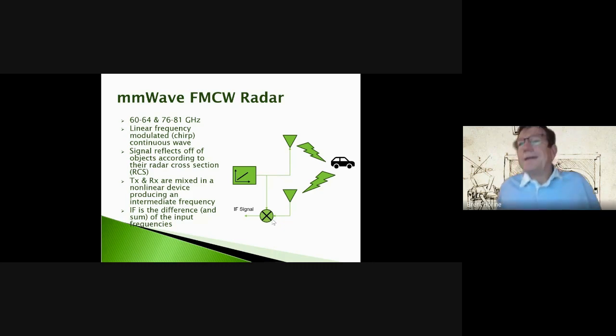I cover this in more detail in my communications course or my microwave course. But what you end up with out here, if you go through all that math with those trig identities, is that the signals at the output of this nonlinear device are the original signals and the squared terms, but also the sum and difference of frequencies, right?